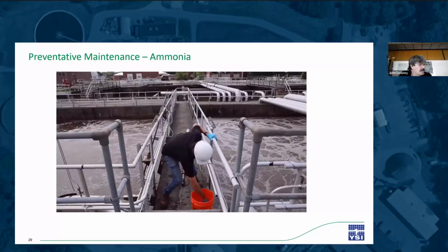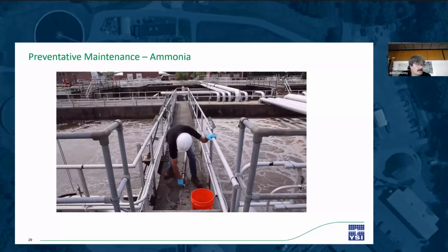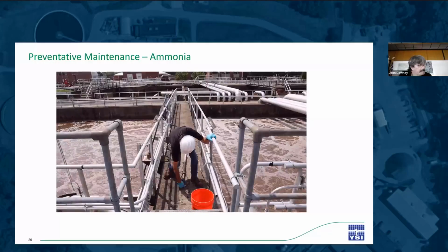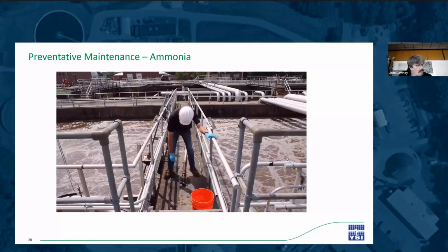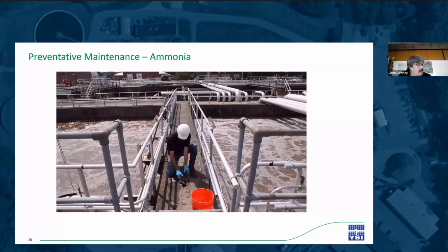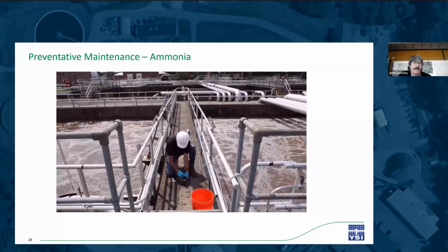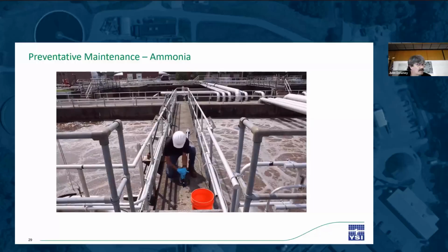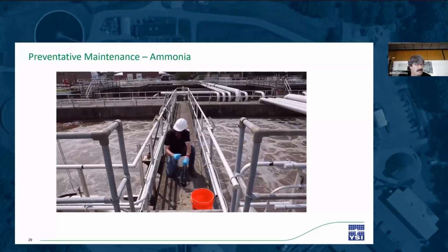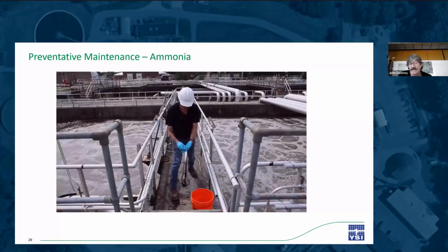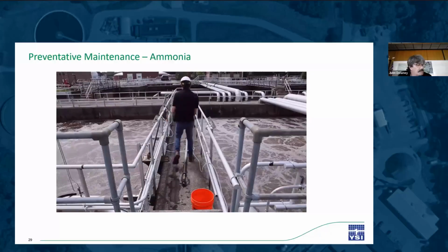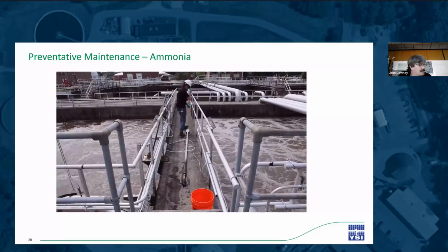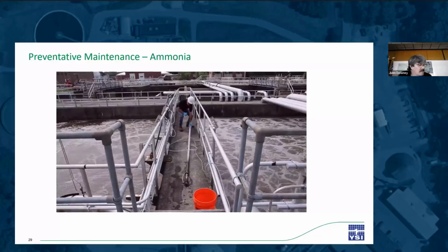Since these are not part of a formal work order system, there's no set schedule. So it really will be an ad hoc situation based on what I'm seeing in the curve, or perhaps a grab sample I might decide to take. pH electrodes, I'll calibrate before installation, and then clean and calibrate quarterly.